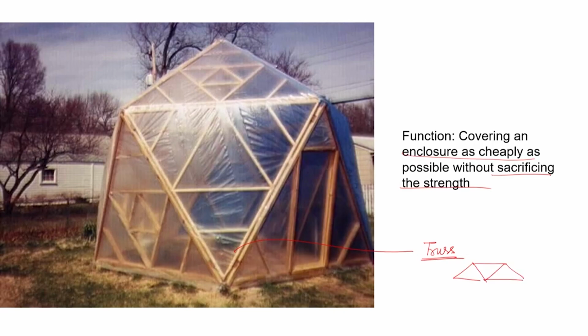like this, which is designed to carry only axial load. That is the idea of a truss. So that is the way it is designed. Even if there are some forces coming here, the forces are going to get distributed only axially through the joints. The joints are all pin joints, they would not allow any moment to be carried. The trusses again are of different types, like determinate or indeterminate structures, etc., that I am not going into the details, but again this particular type of structure has been chosen keeping this functionality in mind.